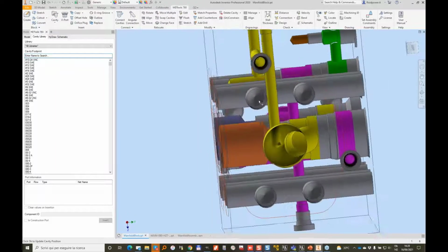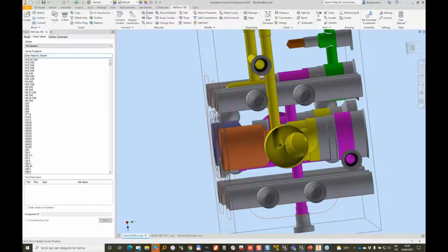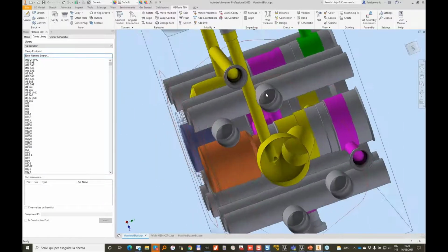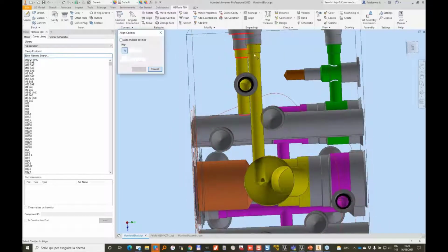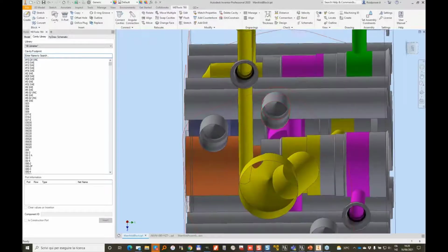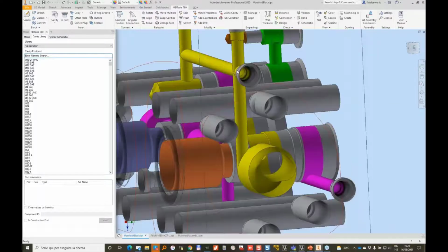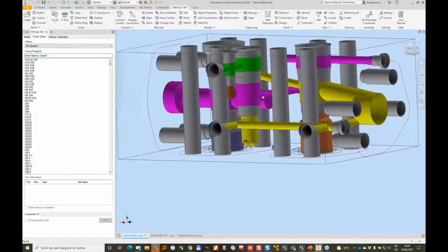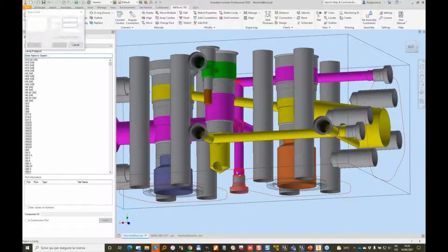This is very close. You can also rotate. Now that may not be an ideal solution, but you can rotate the flange in this case 20 degrees. That's not really a problem. Too much. Now there is an interference, but it will allow me to make a direct center-to-center connection. Remember, center-to-center is always a better connection for intersections in manifold manufacturing. I can just stretch this drill.